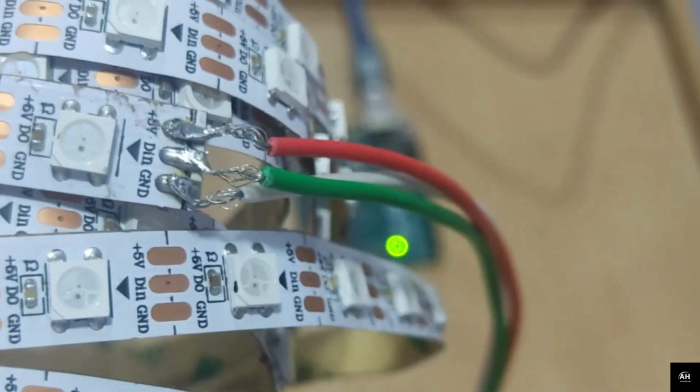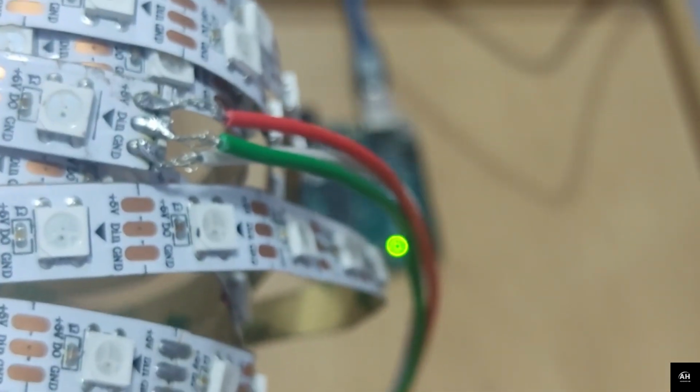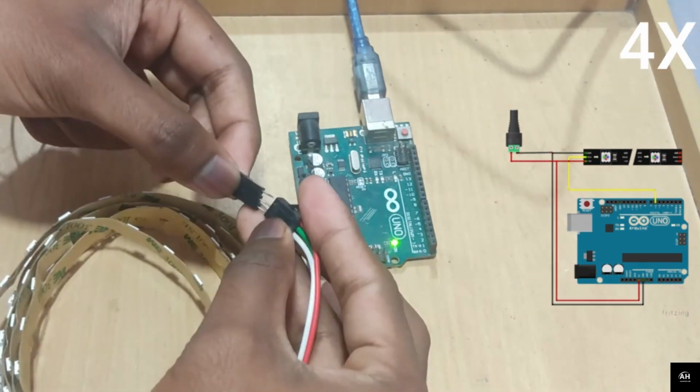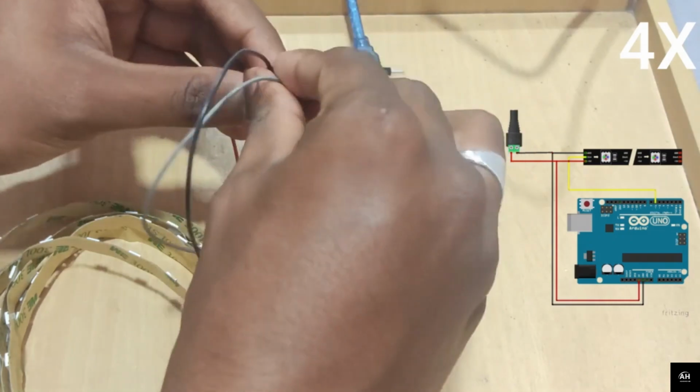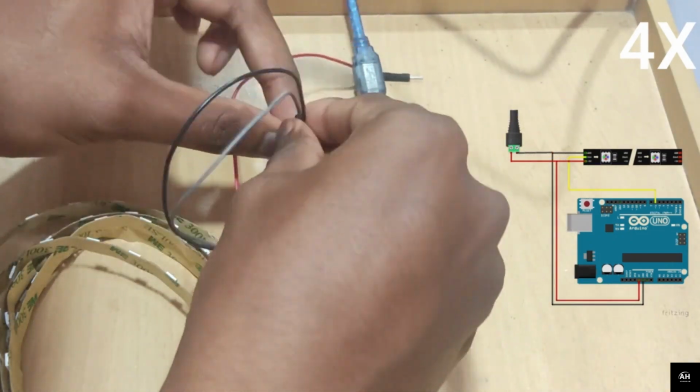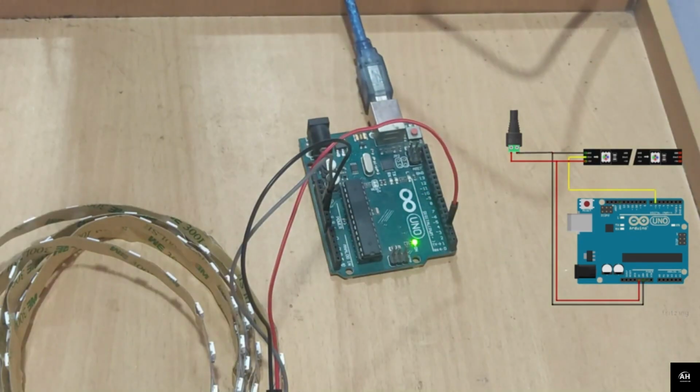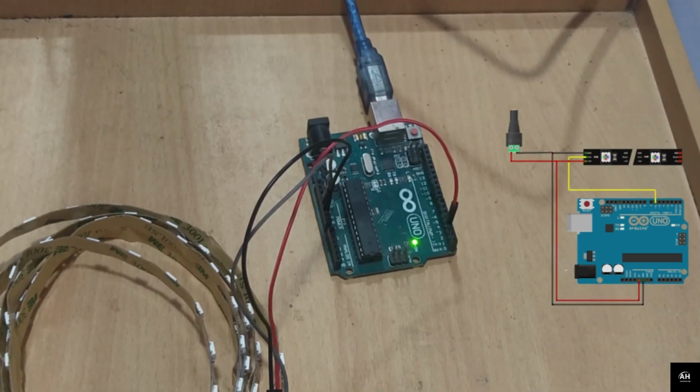So for connecting it with our Arduino board, I will need some jumper wires, and I will just connect it. Now I have successfully connected the RGB LED strip with our Arduino board, and you can see here is the final output of that. And once we are done with the connection, we will move to our computer screen and try to install the FastLED library and try to write the code to control the RGB LED strip with the help of the serial monitor. So let's move to our computer screen now.